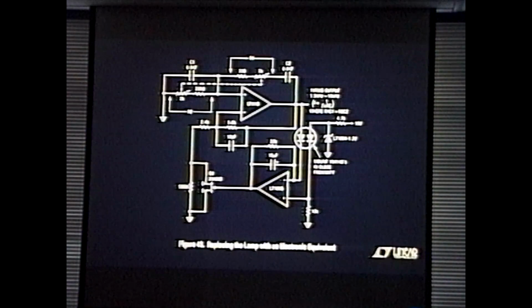In order to investigate that effect, I decided I had to be able to have fine vernier control over the AGC time constant. That meant the lamp had to go. This was my first cut at getting rid of the lamp. You can see the outline. So the name of the game now is to be able to have lots of control over that time constant. What I'm going for here is I'm going to try and beat this thing down on distortion. So I want handles on everything. I want to be able to play with everything.